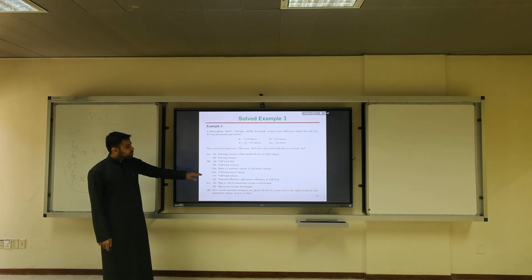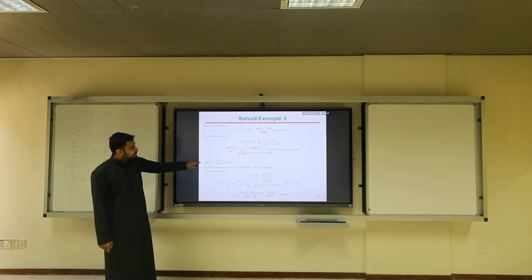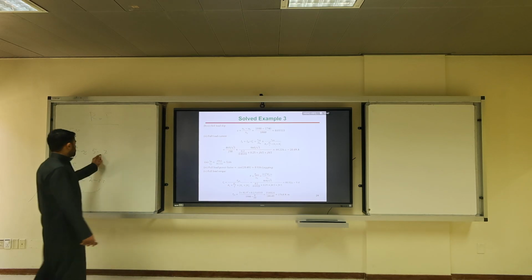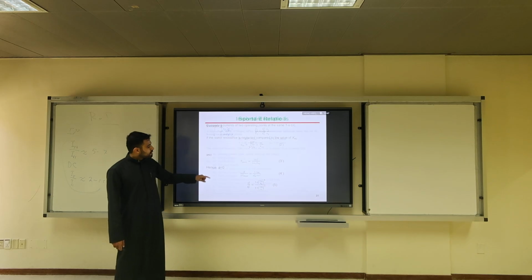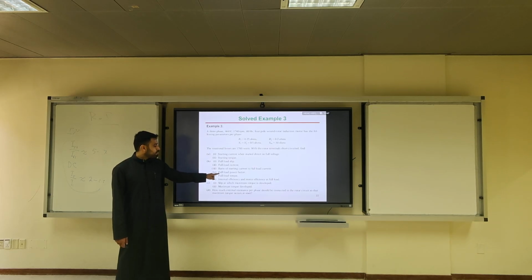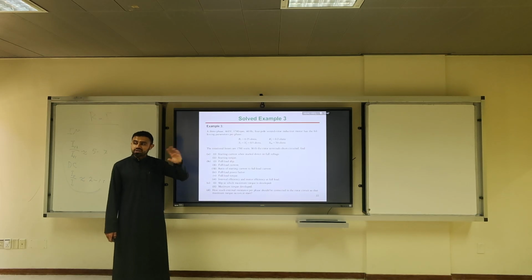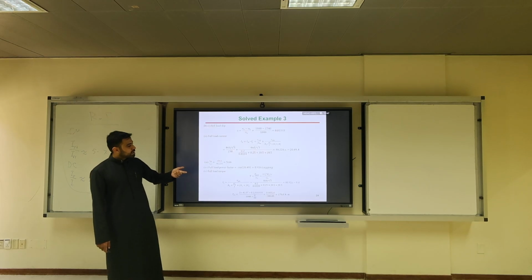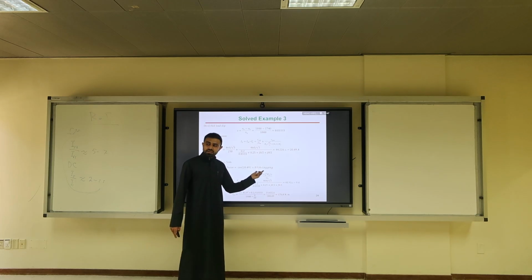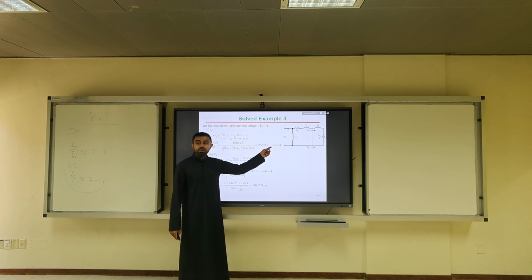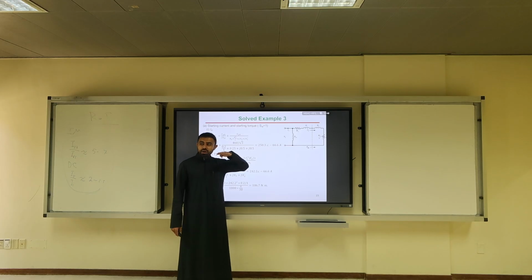What else do we have? We still have to find the ratio between them, which is 5.66. That's within the range, so nothing is wrong with that. Find the full load power factor. Basically, it's cosine of 0 minus the angle of the current. Keep in mind the angle of the current here is 20 degrees, so it is 0.936. However, what is the power factor at the starting torque? It's cosine of 66, which is roughly 0.4. So at starting torque, we have a low power factor.